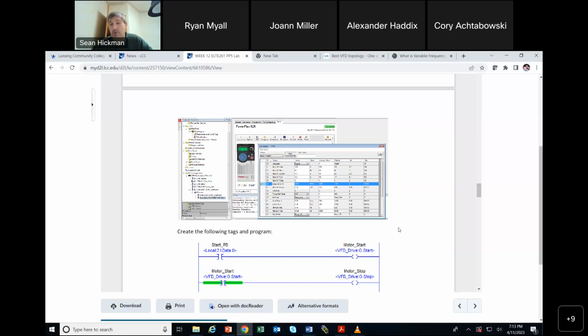I don't remember the name, but I think it'll make up to 230 3-phase. So that's good. All right, that's a good question. I'm glad you brought that up because it's a lot of drives. If you want 230 volts or 460 volts, a lot of drives are just rated up to 230 on the input, and that's what they'll output, 0 to 230. Or if you want high voltage, 0 to 460. It's kind of one or the other. All right, you would want a 230 drive or a 460 drive.